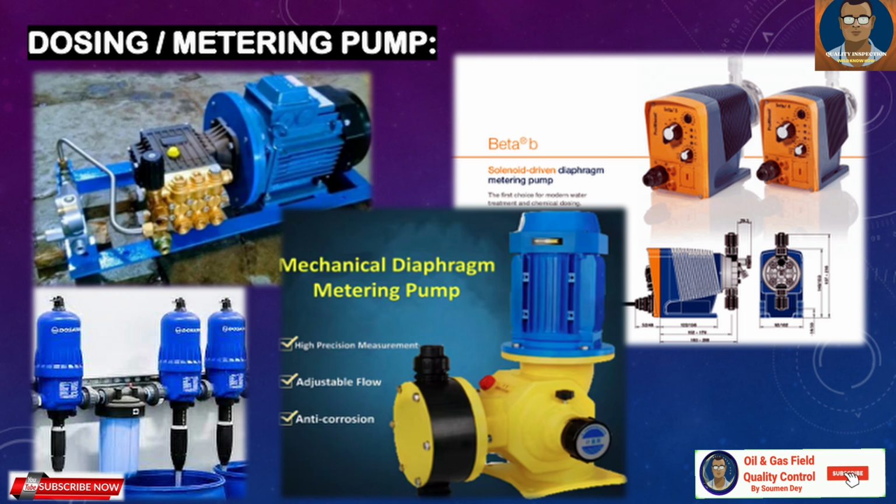Where it applies. For us, it is applied to inject oxygen scavenger and biocides, maintaining a continuous flow rate irrespective of the fluid velocity or differential pressure, maintaining system parameters like pH through the delivery of variable flow, and injecting discrete doses especially for batch processing. Metering is used in various industries like water treatment, waste processing, pharmaceuticals, chemical processing, power generation, oil and gas extraction, petrochemicals, and also, not mentioned here, Hydrotest.